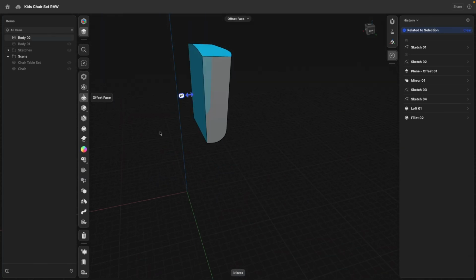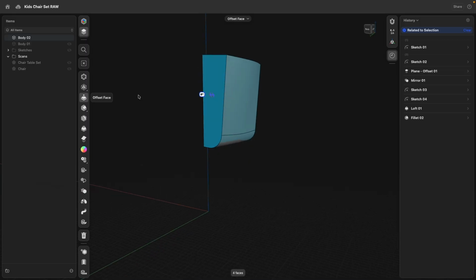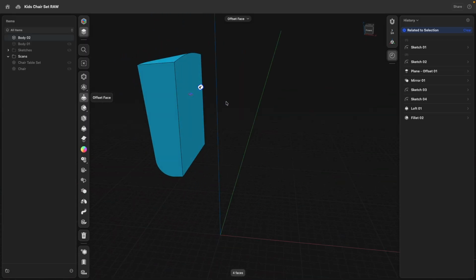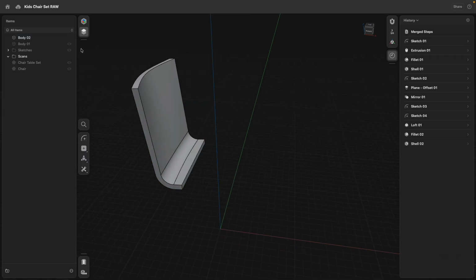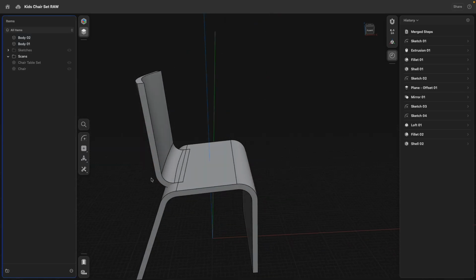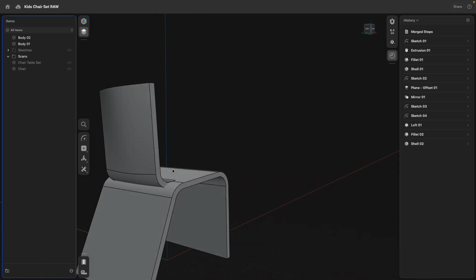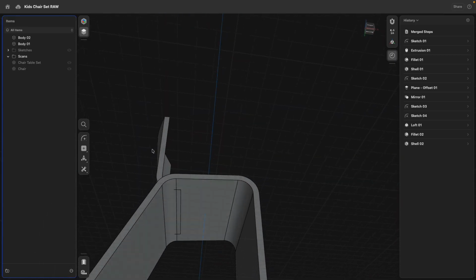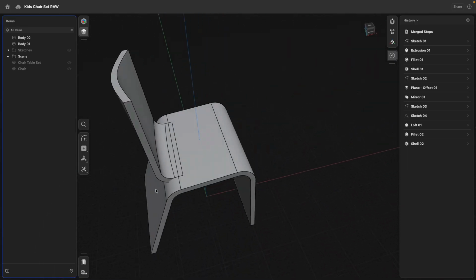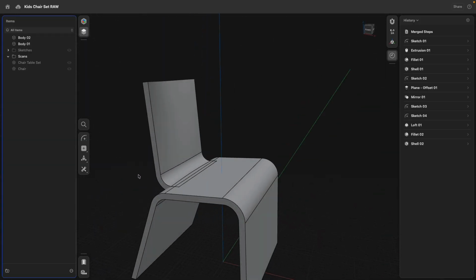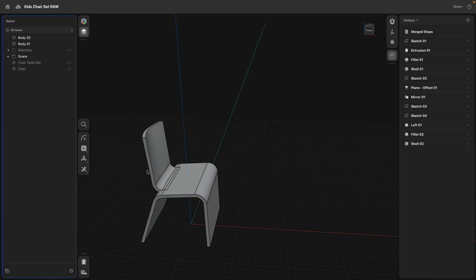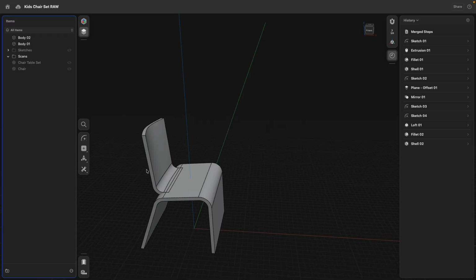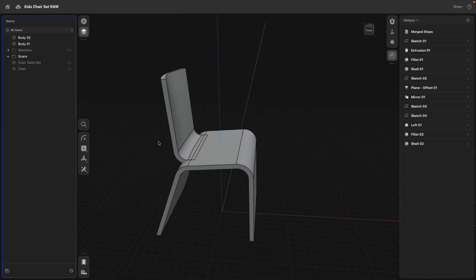And now I can do the same shelling command. The top, the sides, and the front, I would like to shell by 0.6 of an inch. Very good. Now let's show our original base, and there you can see already now how they are starting to flow into each other. Pretty nice, no? Very good. Okay. We're getting pretty close to finish this chair.